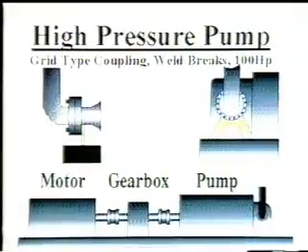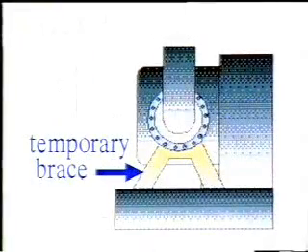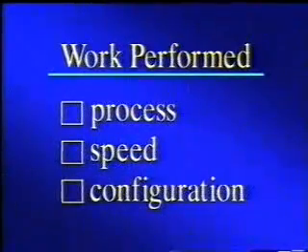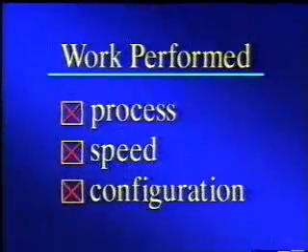A case history involving multi-channel phase data to solve a vibration problem on a high-pressure centrifugal pump illustrates the value of phase analysis. The pump header repeatedly cracked, causing a shutdown of the manufacturing process. A temporary brace was installed to help remove the strain on the header, but it cracked again. No other work has been done on the machine, and the process, speed, and machine configuration were not changed.